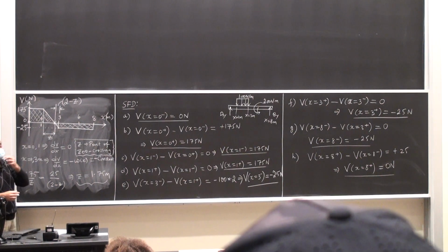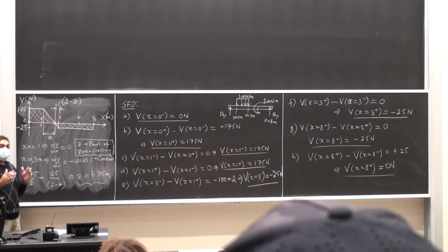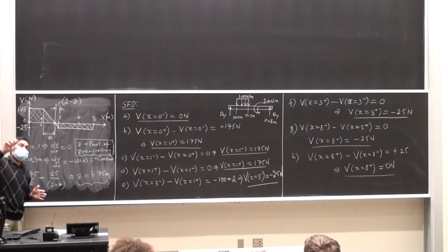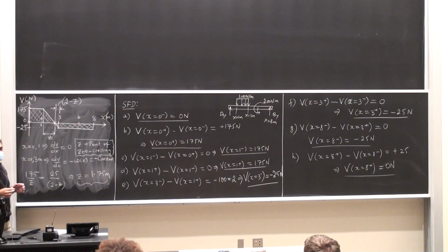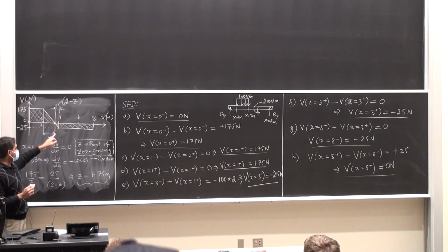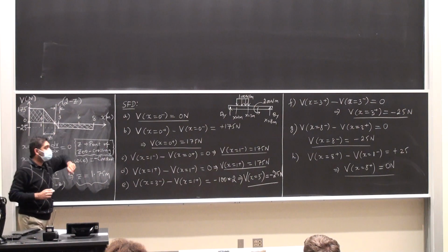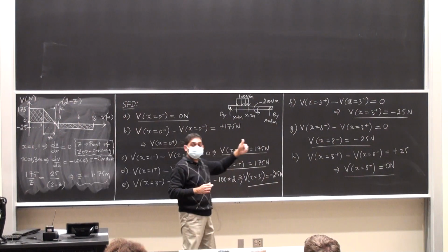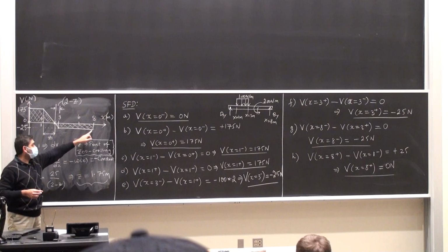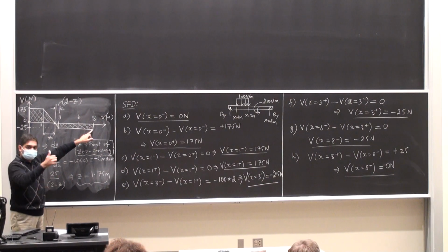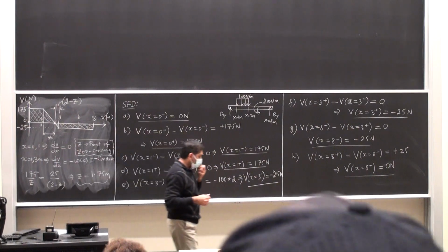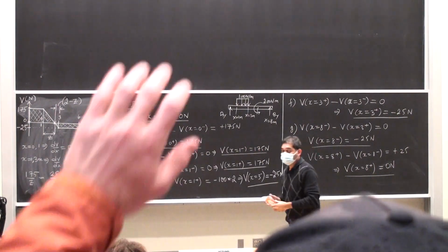It crosses the x-axis at a point, the point of 0 crossing. If the shear force crosses the x-axis, at that point the bending moment is either a local maximum or minimum. I find that point using similar triangles. Then I say, okay, I need to just go to the end of the beam because nothing special is happening in between 3 and 8. I go to 8 minus, it's minus 25. So I'm right here. Then I see I got to go home, climb up. Okay, perfect. We're going to get the bending moment curve. Okay, that's a little more complicated.